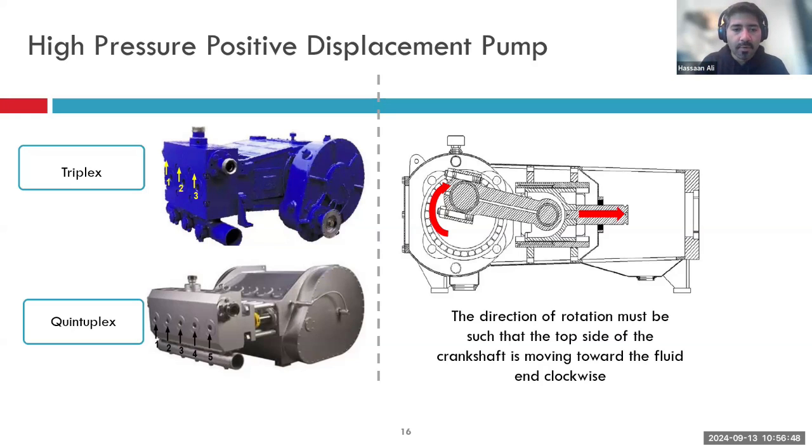A common failure mode is packing failures, seal failures, a ruptured disc on a suction valve being damaged. Then similarly, issues with your gearboxes, issues with the power end of the pump. So these are some of the common failure modes on these pumps.